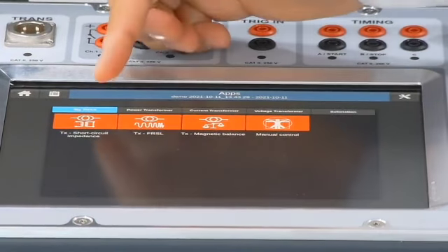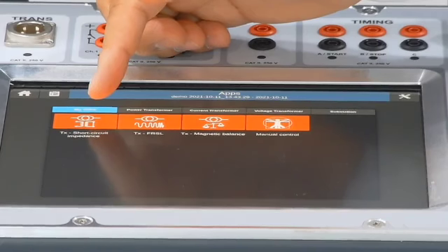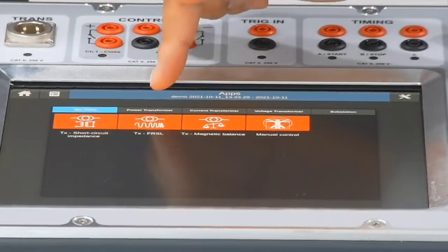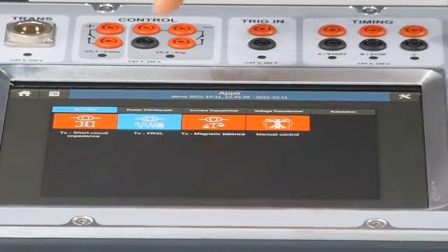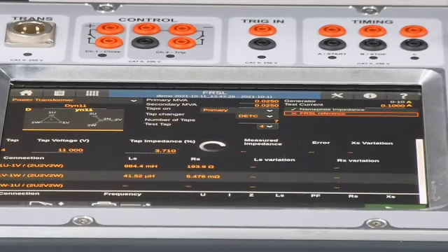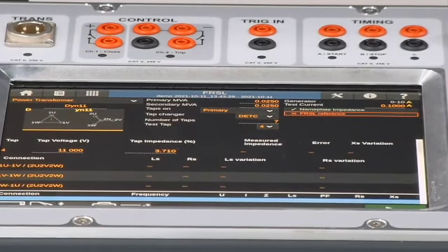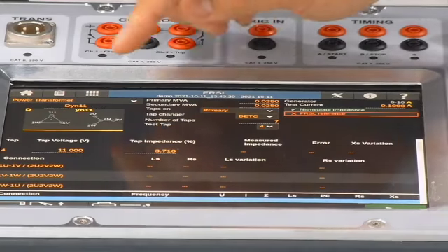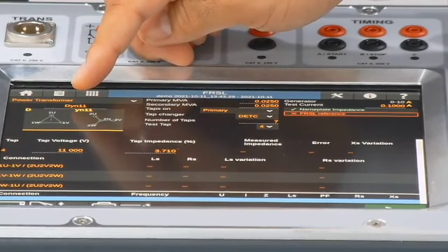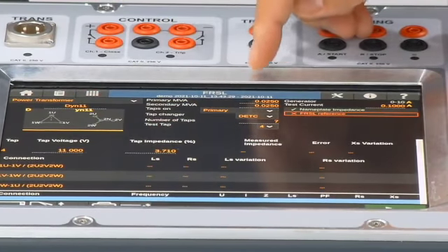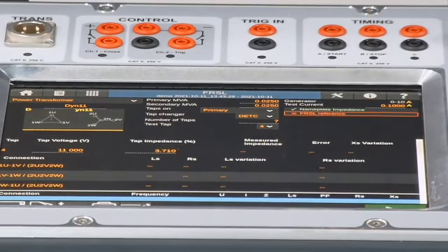And as I said in the beginning, I'm running short circuit, and then I will move to frequency response of stray losses. I will go there. This is having exactly the same connection as the previous disk, which is the short circuit. I already copied, or the system copied the vector group from previous disks. It's also copied all other parameters that I don't need to re-enter.